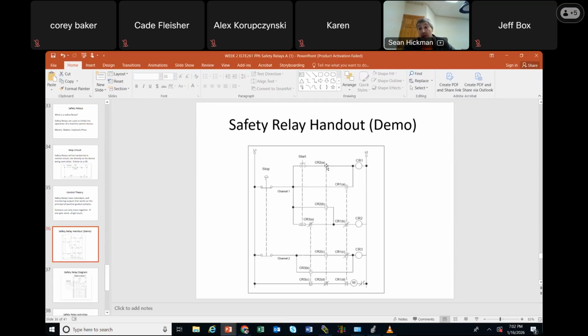they're used when you need a higher level of safety. In a lot of places you need a higher level of safety. When you want to turn that motor off, if you need to turn it off, you need to be sure that it goes off. Whereas if you just have a simple start-stop and something gets fused on, you can't turn that motor off without killing the power. But if you definitely need to turn it off, most times safety relays are red. A lot of things do have these safety relays because it's a higher level of safety.